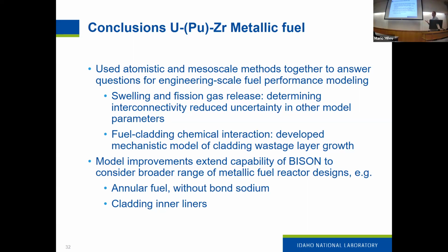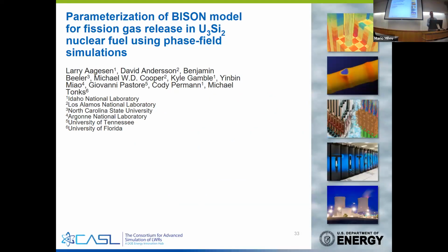Some of those types of designs would be things like annular fuel, where they don't use bond sodium and the fuel expands more inwards. Also cladding interliners, which is something Ben and I are working on, where there's a diffusion barrier. So this type of model can be used much more effectively to extend to those new types of designs.